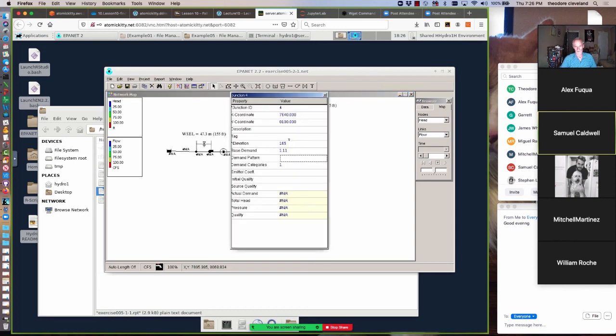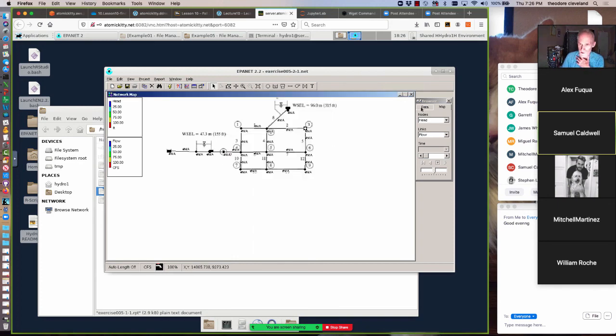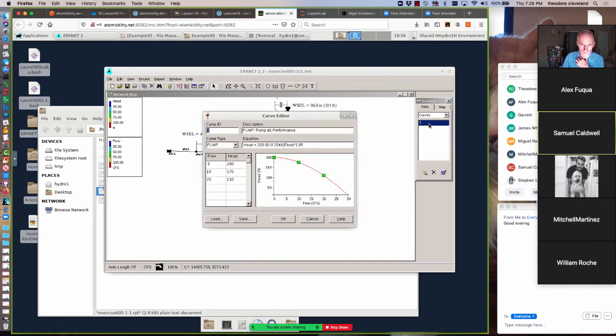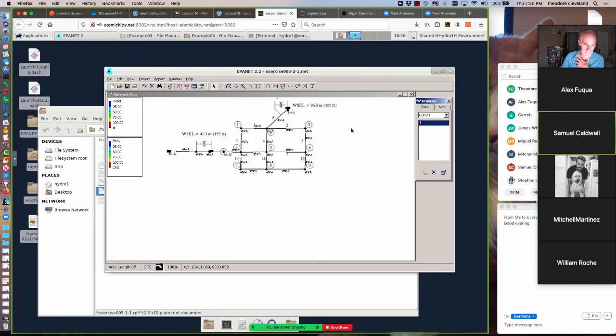So we would provide elevation, any demand. This one's in CFS, so let's hope the pump curve for this one is in CFS. Yeah, whoever did the pump curve left it be. That was me. So that means I converted 9 nodes from gallons per minute to cubic feet per second. That's not the brightest move I've made, but it's correct. I mean, it will work.